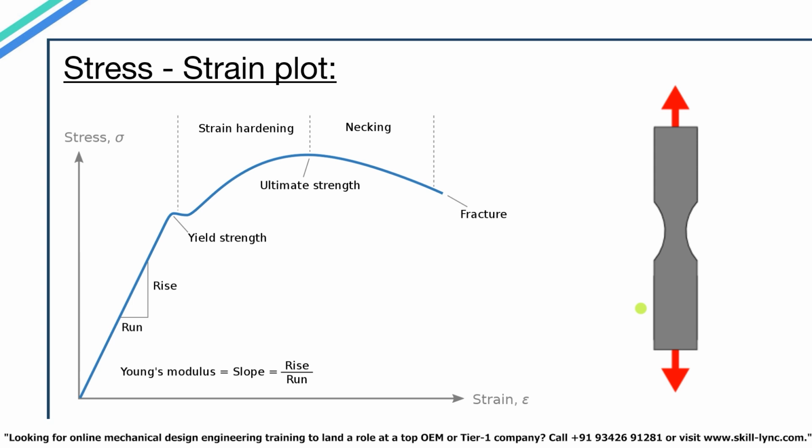Also, when you perform any type of analysis, the software needs to be provided information regarding how the material will behave when a load is applied. If we apply a load of 100 Newton on a steel beam, or if we apply 1000 Newton, then the simulation results will obviously be different. But the software is able to create a proper simulation for the material because the information of stress-strain plots is already added to the software. So a user would just select the material for the model and the software will predict accurate behavior based on these experimental results.